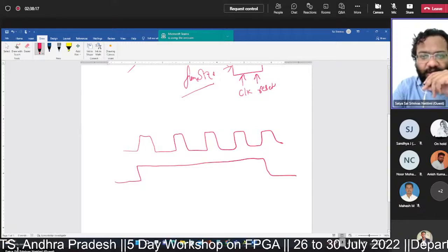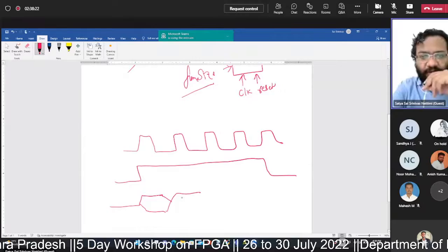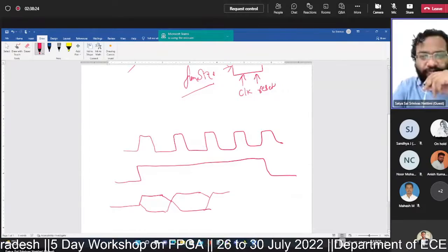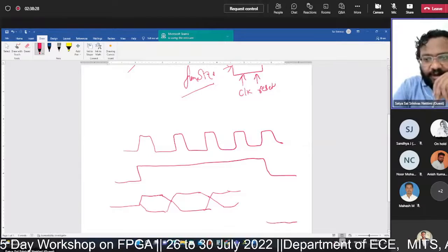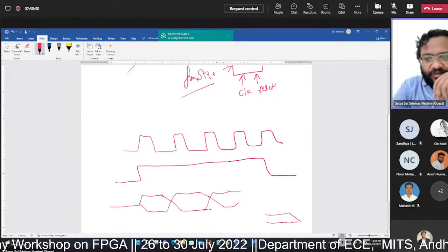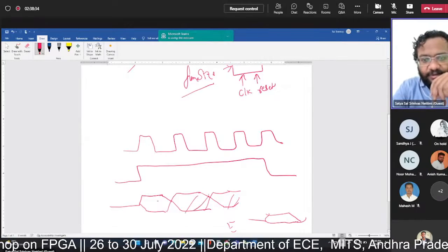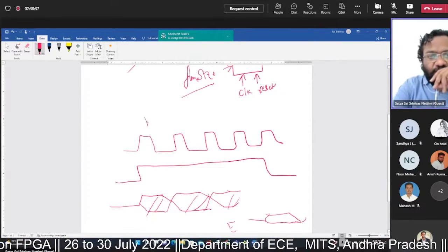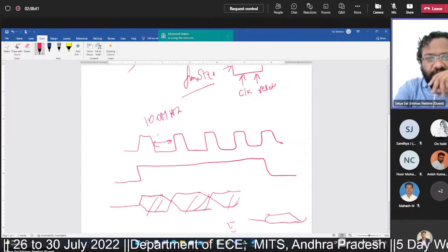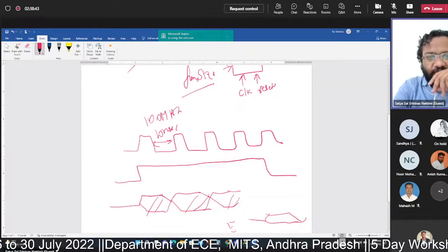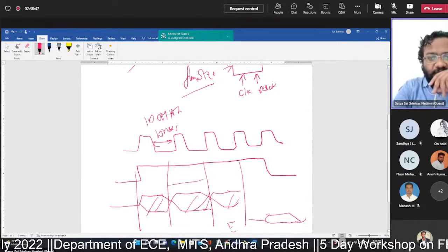It to be high, and on every clock edge we gave a new data sample. And ultimately we calculated the frame energy. This is the energy, this is the data sample. And we know that the clock is working at 100 megahertz and the time duration of the clock is 10 nanoseconds. So for every 10 nanoseconds, we have to give one sample of a signal.